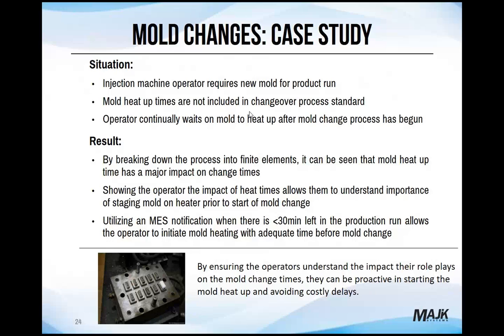And you can see that occasionally, or more often than not, the heat up time is not actually being included in this mold change procedure. When you show the operator the impact of the heat times, it allows them to understand the importance of making sure that that mold is staged prior to the actual change procedure.